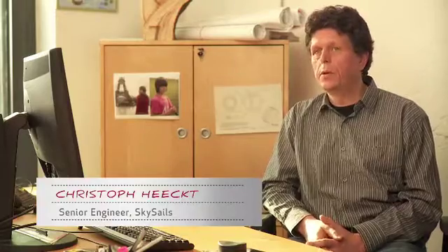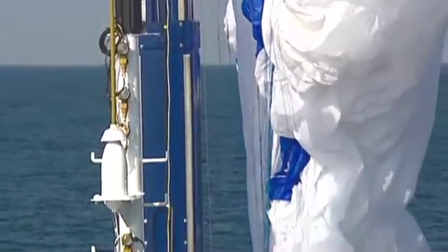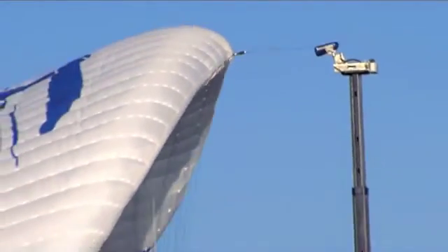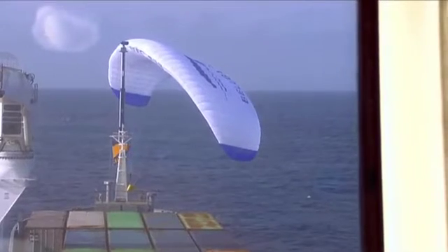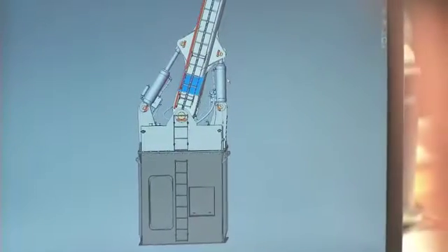The ship usually rolls by plus/minus 20 degrees, and it goes up and down by plus/minus 5 meters. The mast length is approximately 25 meters, and you can imagine how much movement we have at the top of the mast. That creates a lot of forces which we have to handle. We had stress problems at the beginning, as we expected.